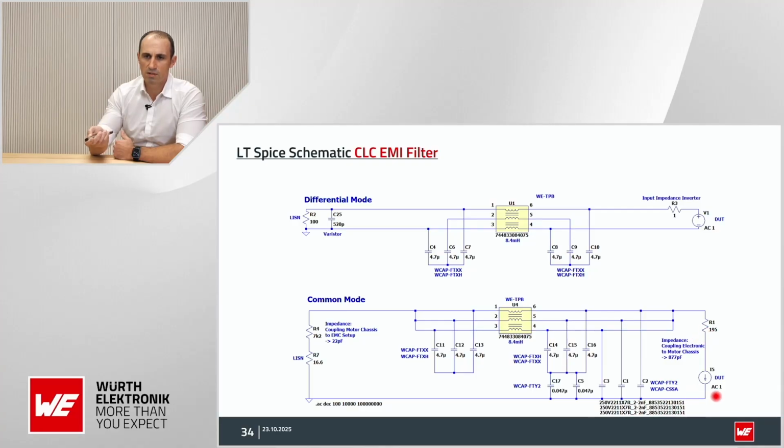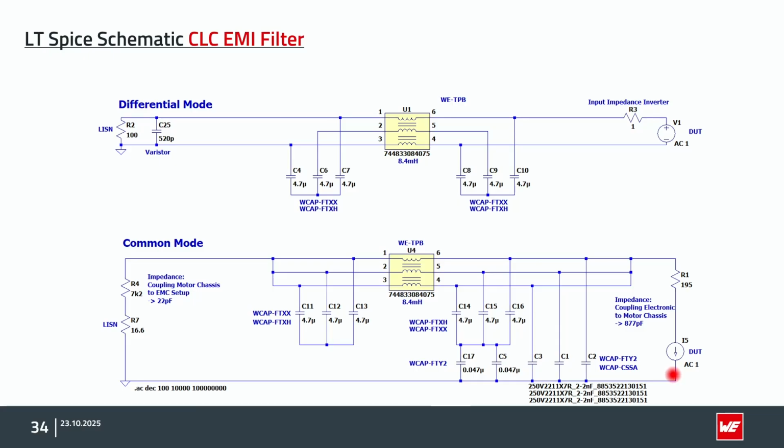And we are using not a voltage source, but a high impedance AC source, because common mode suffers a high impedance source, as I already told you. And we put in the Y capacitors against ground. Ground is in this case protective earth. And you have to shunt the three lines on the common mode choke together to get the main inductance against the protective earth.